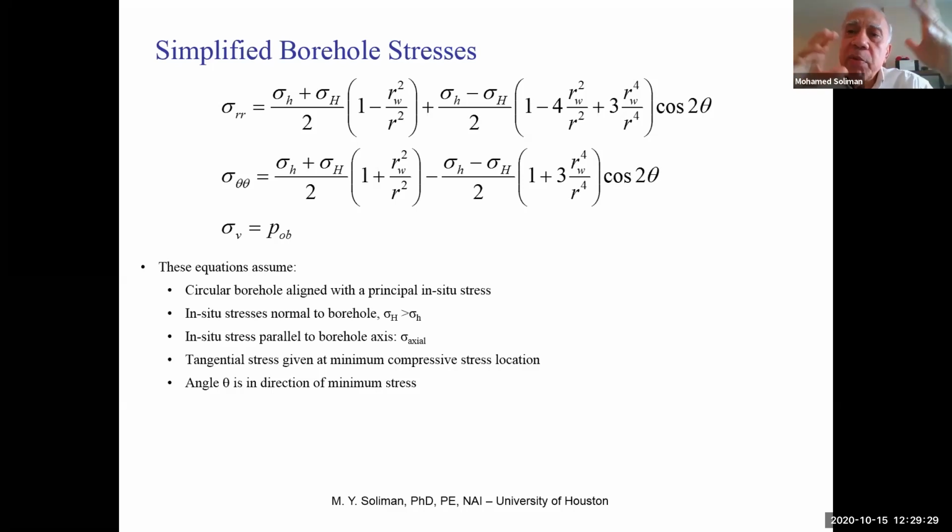My group worked on the rock mechanics side, and other groups worked on the electrical and mechanical parts. You go in and inject fluid and balloon the wellbore, so you don't observe it by eye, but you measure the ballooning behavior, the fracturing process and the widening of the fracture.